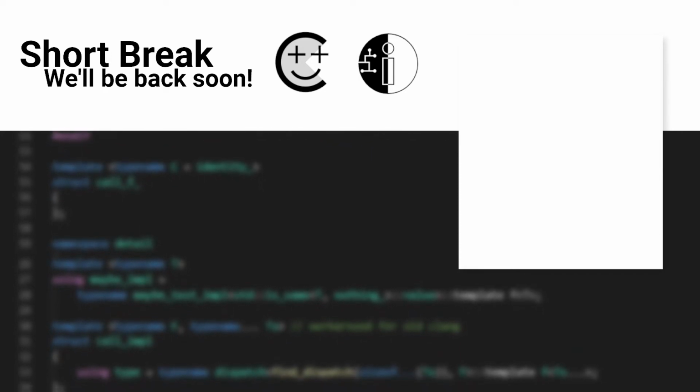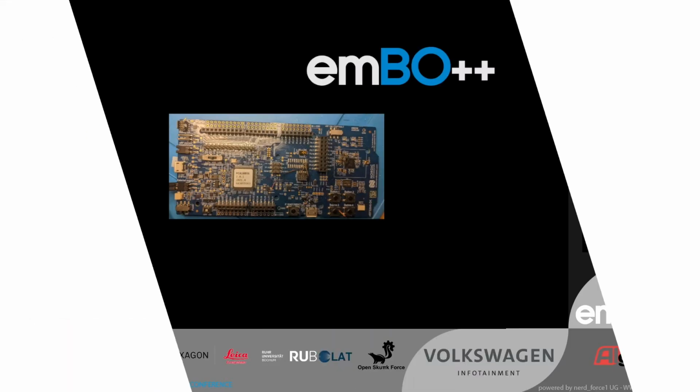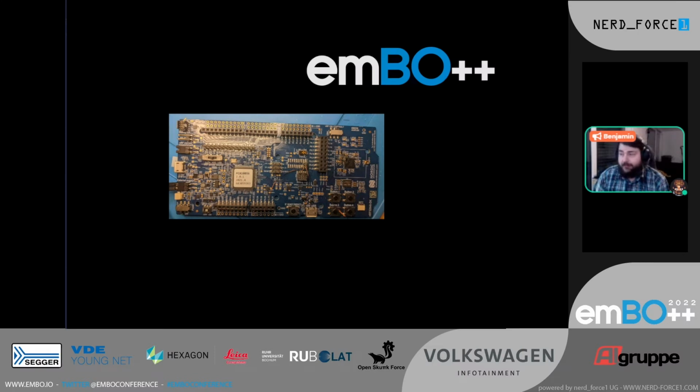Instead of reading it, let's just test what happens. So we connect to our dev board, we try our usual things, we lock the device, we connect the Segger probe, and well, J-Link Commander complains that the device is locked. We, of course, ignore the error and just say continue, and we hope we can still single step, we can reach the registers, but no such luck. Just no connection is possible. So we have no way to influence the state using software attacks. Well, that is why I actually had to switch to hardware attacks for this one.